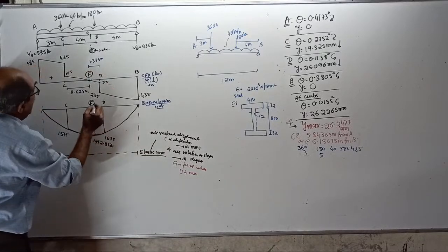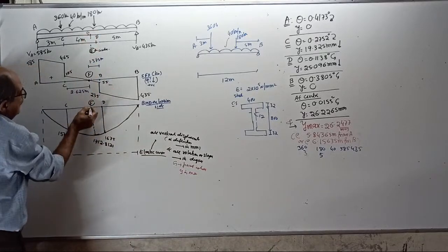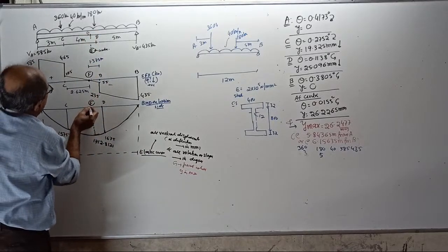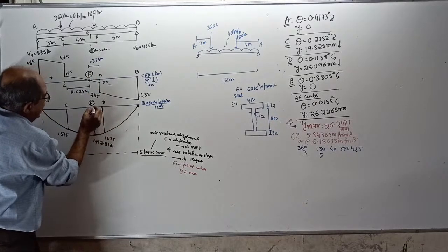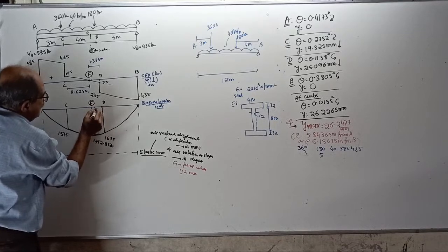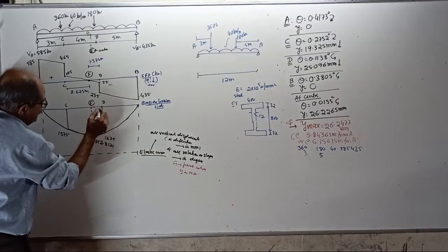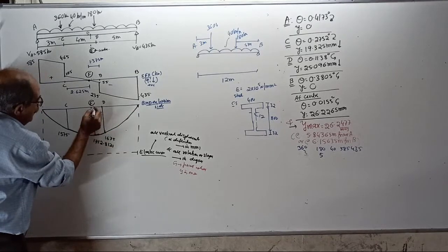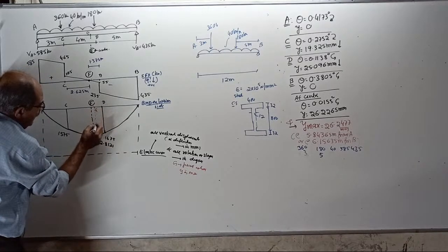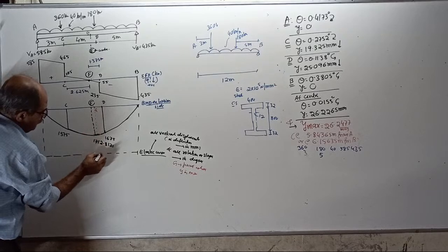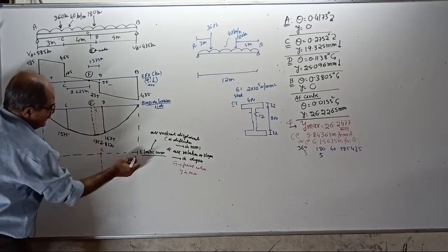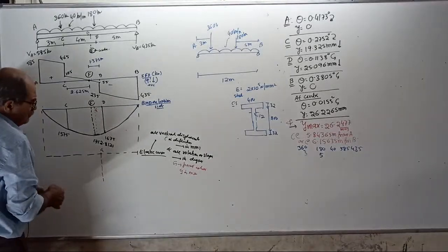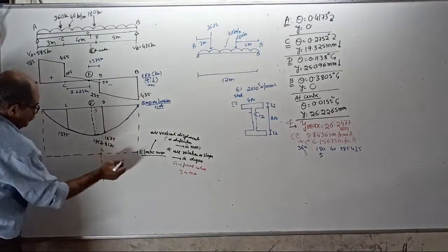That point lies slightly right of F, but before D. This is the point G. So there deflection is maximum. So why do you think? When I draw the elastic curve here, this is the point G, maximum deflection. The elastic curve will come as a smooth curve.